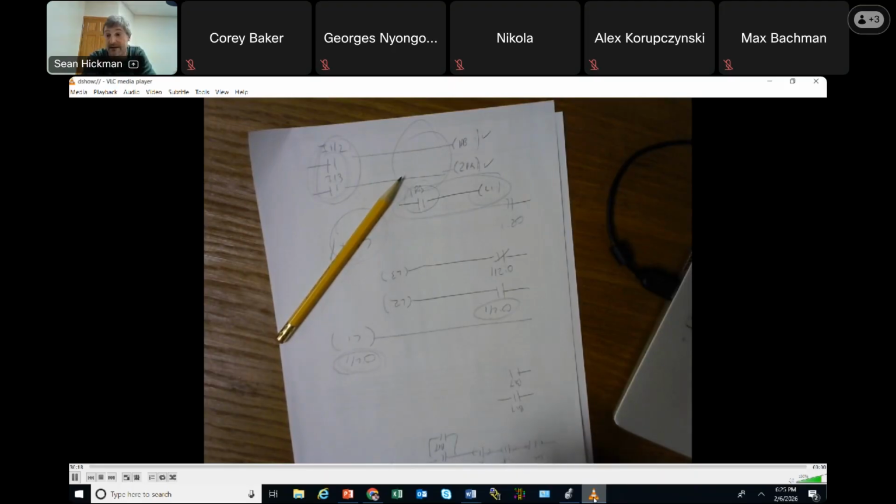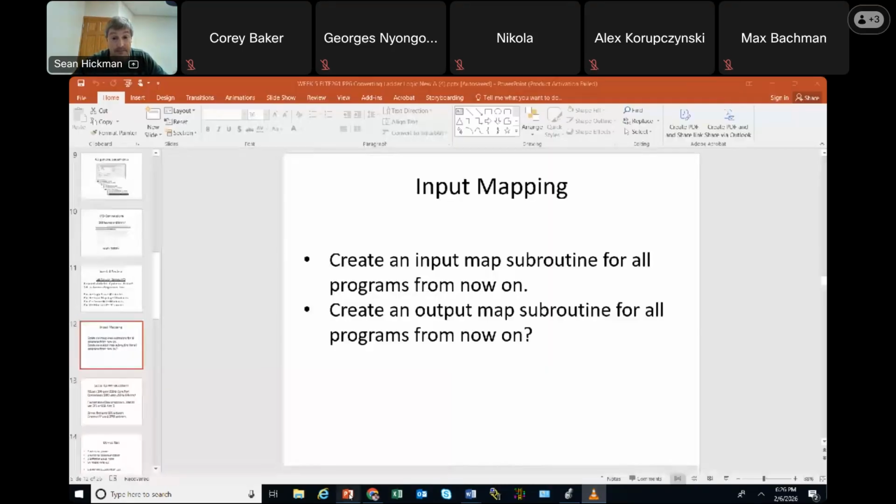And we looked at the ladder and we like, okay, maybe this weird situation happened. And what we did is we mapped the inputs so that stuff couldn't be true and false at the same time. And then it works fine. So it does happen out there, okay? So you got to map your IO.